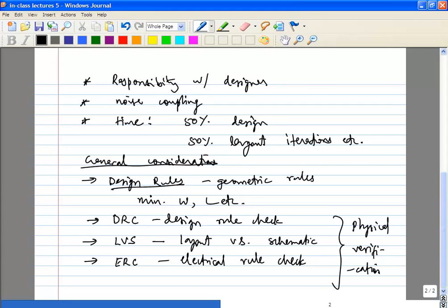Okay, so for example, let's say a lot of modern analog processes or even digital processes have two power supplies. So they'll have what is called a thin oxide transistor. If you take a 65 nanometer process, for example, or a 130 nanometer process, you'll have a transistor whose minimum length is 130 nanometers and its gate oxide thickness is a certain amount, and you'll also have what are called IO transistors. Okay, those will typically be larger. So the minimum length on those may be, let's say, 0.25 microns, 250 nanometers, and the corresponding oxide will be thicker. Okay, the corresponding voltage supply will be higher for those transistors. For the 0.13 micron transistor, we are using 1.2 volts. The other one may be, let's say, 2.5 volts or 2 volts.